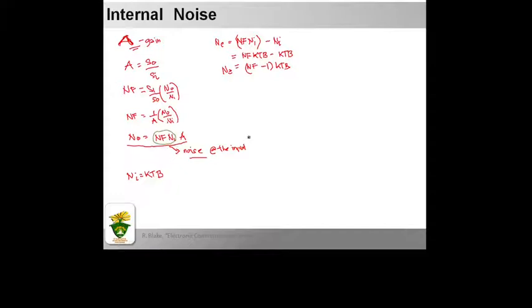If we suppose that this noise is generated in a resistor at temperature T equivalent, and we further suppose that the actual source is at reference temperature 290 Kelvin or 27 degrees Celsius.